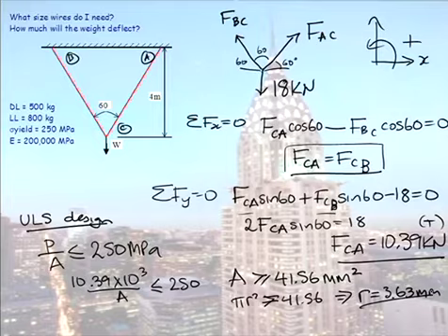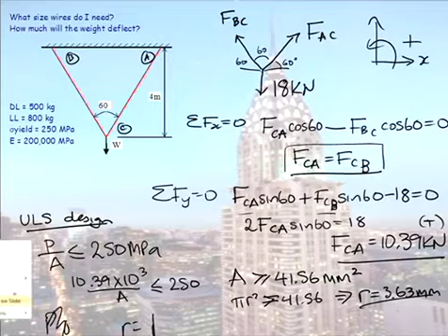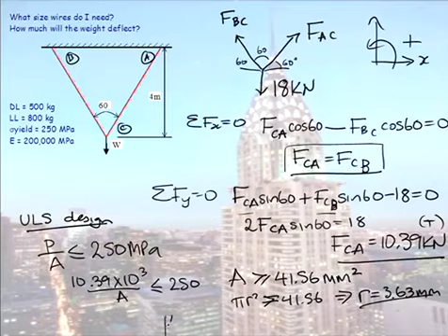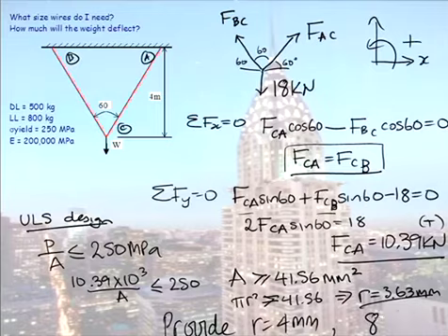So let's say here the radius we can buy is, so I'll write provide. Let's say provide our radius is equal to 4 mil. So 8 mil, I don't know if you know, a circle with a line through it means diameter. So let's go buy some 8 mil diameter rods, and this thing won't fall down.